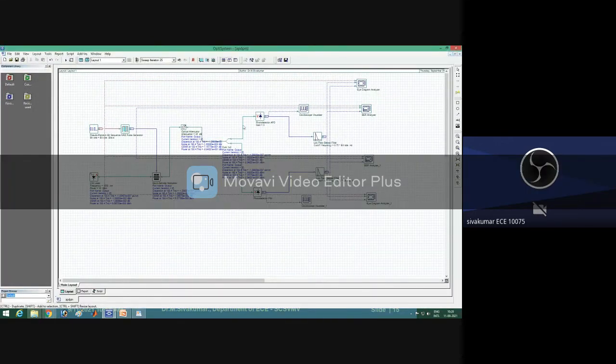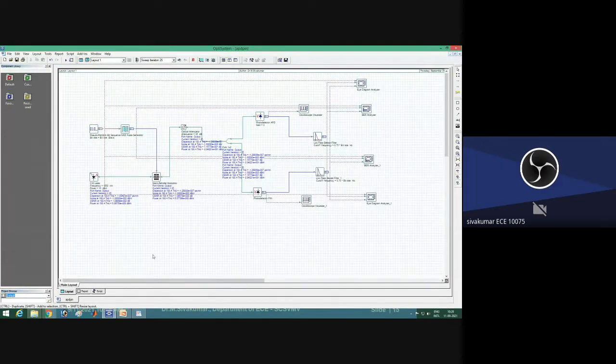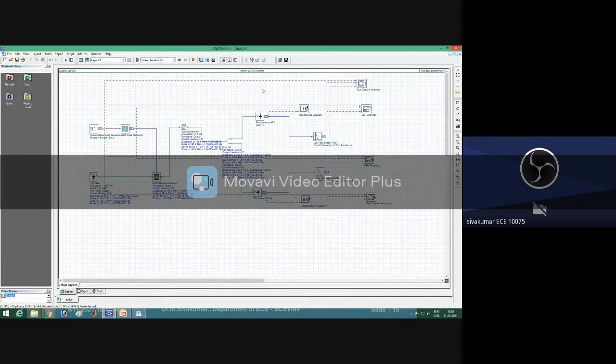There is some problem, so it is not able to show this photodata. Here also you can see the noise levels, thermal noise and shot noise. Here you can see the input optical transmitter side. You can see how many iterations, what the dispersion is at 193.4 terahertz, and what the OSNR rate is. All the things are given here. This is an eye diagram analyzer. After running the simulation,